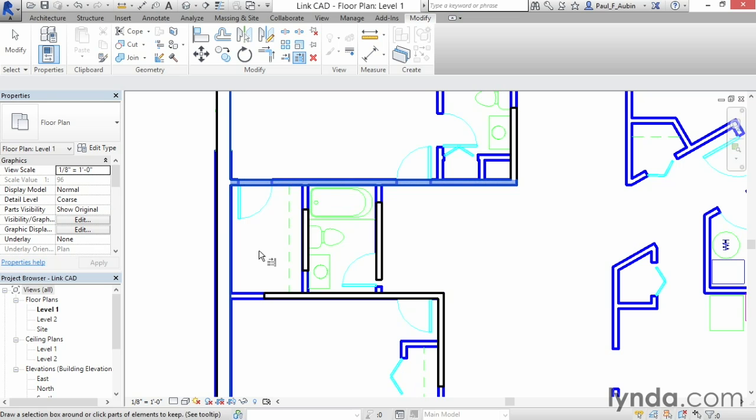The boundary is still active. So if I click on a second wall, it will continue to extend over to the same location. Now, at this point, I've got all the walls I wanted to extend over to that wall, and I want to choose a new boundary. The way you do that is to simply click an empty white space, and that resets the command but stays within it, and then you can pick a new boundary. Now, with walls, it doesn't actually matter if you click this side or even the center. The entire wall will be seen as the boundary edge.